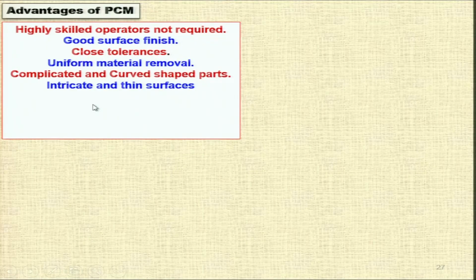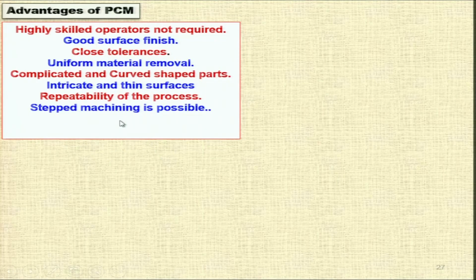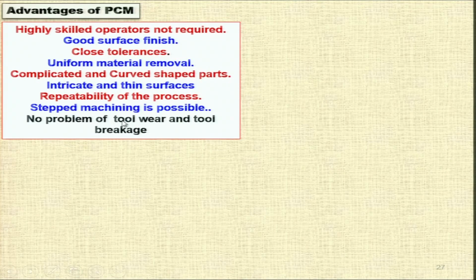Complicated and curved shaped parts can be made by this. Intricate and thin surfaces can be obtained. Repeatability of the process is good. Stepped machining is possible. We have seen stepped components already and tapered components. No problem of tool wear and tool breakage, as we have seen in case of conventional or traditional machining processes.